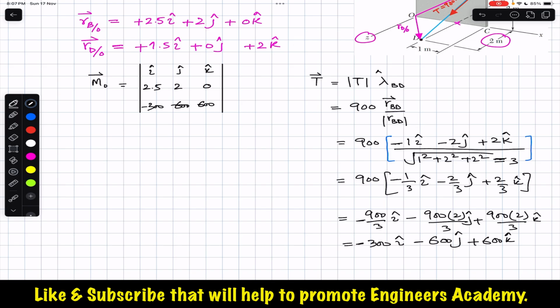So this will give us the moment vector about point O once we evaluate this determinant. For i, we have to hide this row and this column. So 2 into 600 minus 0 into i. For j, we need to hide this row and this column, and with j always comes the minus sign.